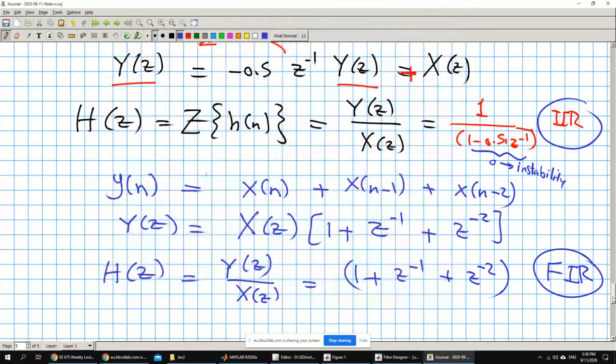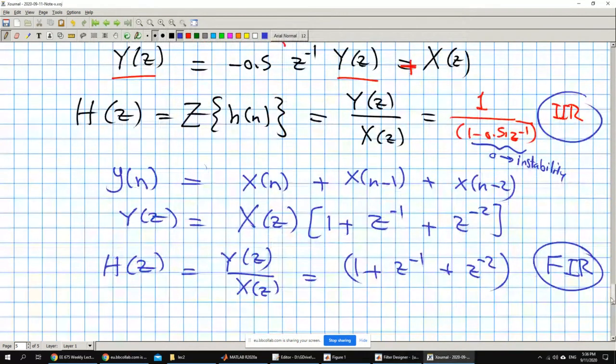So both of them will also have a transient response, Doctor. IIR and FIR. Yeah, they are both digital filters, yes. Both have the transient effect. Definitely they do, because you have the same problem: the length of the filter has to be entirely inside your signal in order for you to get the correct output. So as long as the order is large, you're going to have transient. So both will have transients definitely.